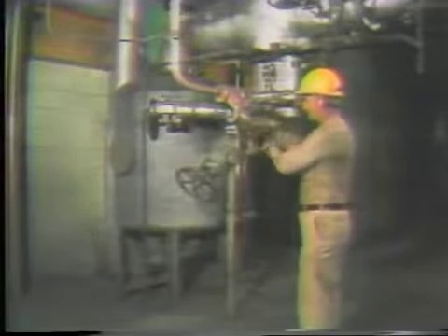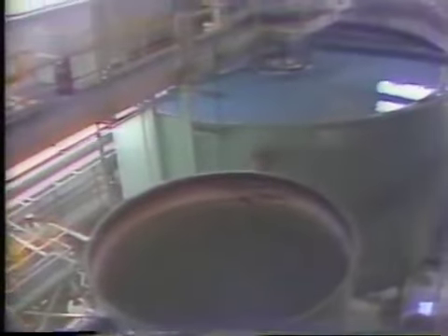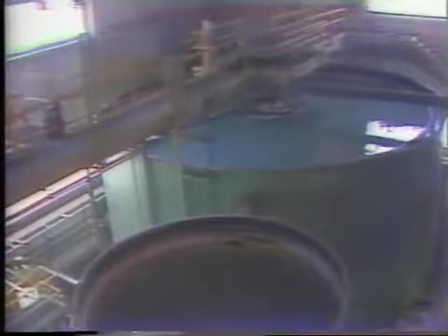The third source of pollution that we need to cover is wastewater. This comes from various plant equipment and especially from the boiler in the form of blowdown. Blowdown is necessary to plant operation in order to get rid of silt and other impurities. But along with silt, blowdown often contains chemicals. If these chemicals are discharged without being treated, they might harm the environment. You need to make certain that wastewater is properly treated before it's discharged. Each plant has its own wastewater treatment system, and you'll have to know how to operate yours.